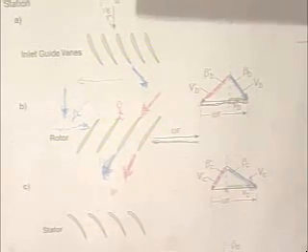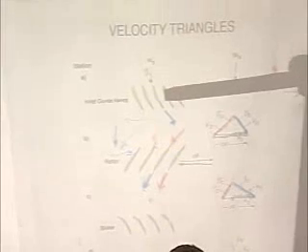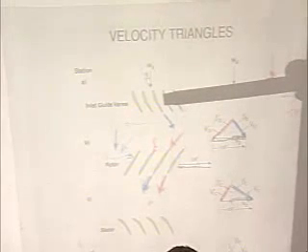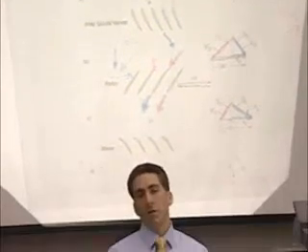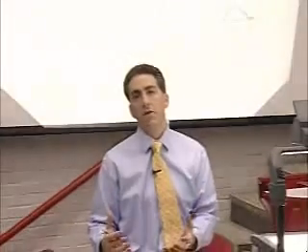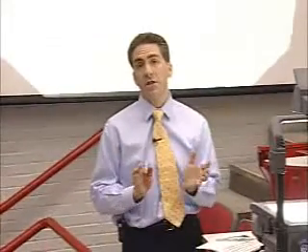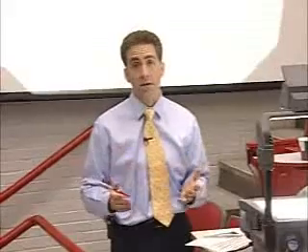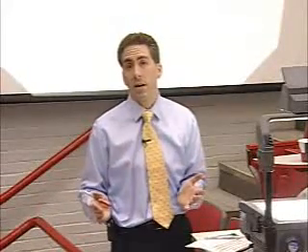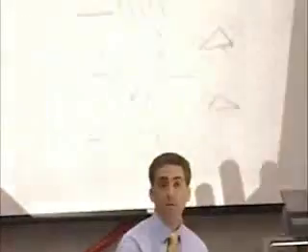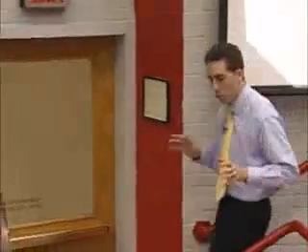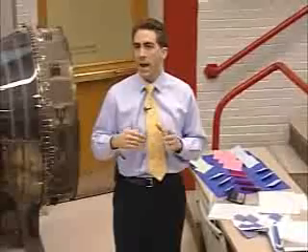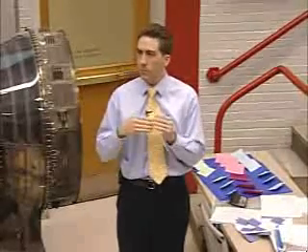There is no work done over the stator. There are forces, but since it's not a moving blade row, there's no rate of applying the torque, so there's no power added to the flow. They just change the direction. So you get forces, and you calculate those in homework, but since it's not a moving blade row, no power added. Right. This is a lot of sort of complex ideas all at once, and the only way to do it is to practice it. Okay? And the rules will be good to you.